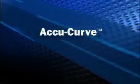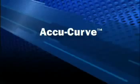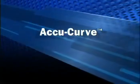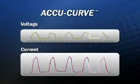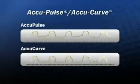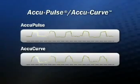AccuCurve is another variation of the AccuPulse process. The process still uses the same CV adaptive scheme and waveform topology as the AccuPulse process. The main difference is the current transitions from peak to background and from background to peak. In AccuPulse, they were done with linear CC transitions of amps per millisecond.